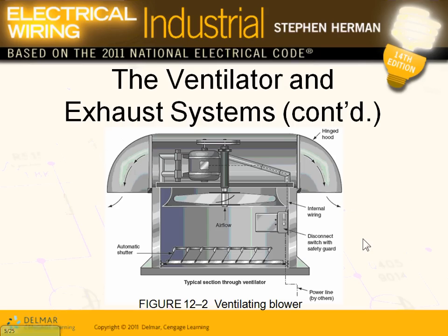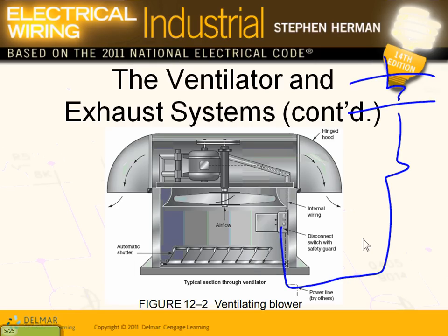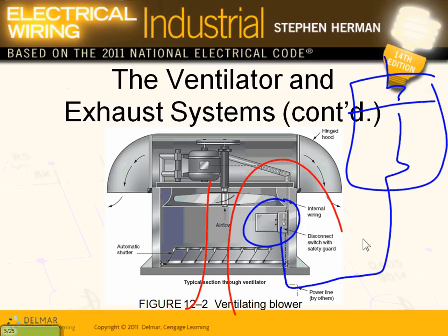Okay, then we have ventilation exhaust fans. Again, guys, our job is always to bring the power to the equipment from a panel. That's the only job that you have to worry about. You have to have a disconnect for this equipment because it's mechanical equipment. What they do is circulate the air, guys, from one point to another. You grab the air here, and you exhaust it. When we go to Allianz, you guys are going to see a bunch of these exhaust fan units on a roof in different locations, so they can exhaust the air.